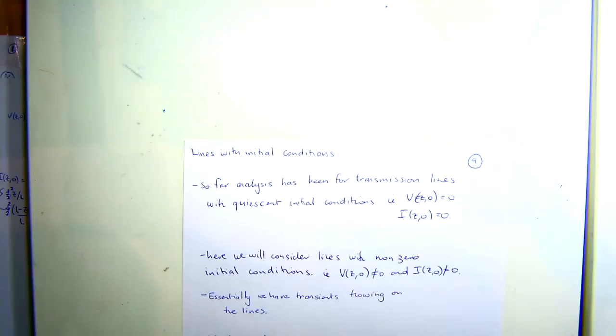It's called a Cockcroft-Walton generator. Essentially, you connect a collection of diodes and capacitors in a particular way so that you actually get voltage multiplication. You pump it with a small sinusoidal signal, and it's something like this.